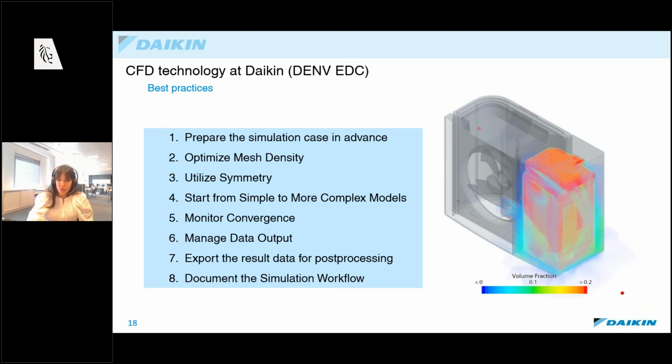Document the simulation workflow, maintain detailed documentation of the simulation workflow, including setup parameters and solver settings. This facilitates reproducibility, collaboration, and knowledge transfer. Maybe it sounds like an obvious thing, but when you're trying different things or you start to have problems with the simulation and you keep changing things, sometimes it becomes hard to remember what we were doing and what we changed at the end.